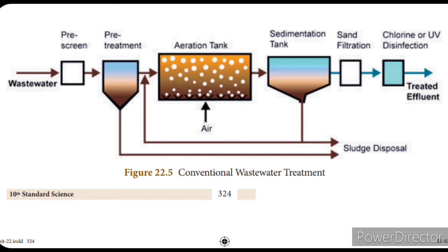Right now here the microorganisms are removed by biological degradation, and this takes place in the presence of air. Next is the sedimentation process. Sedimentation in the sense of settling down. In this process, the solid particles present are allowed to stand in a tank for hours together, so that the particles settle down and the suspension is removed as sludge.